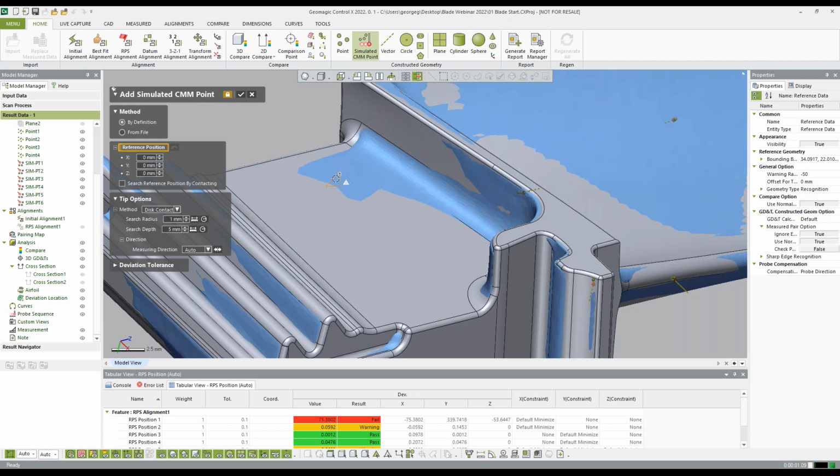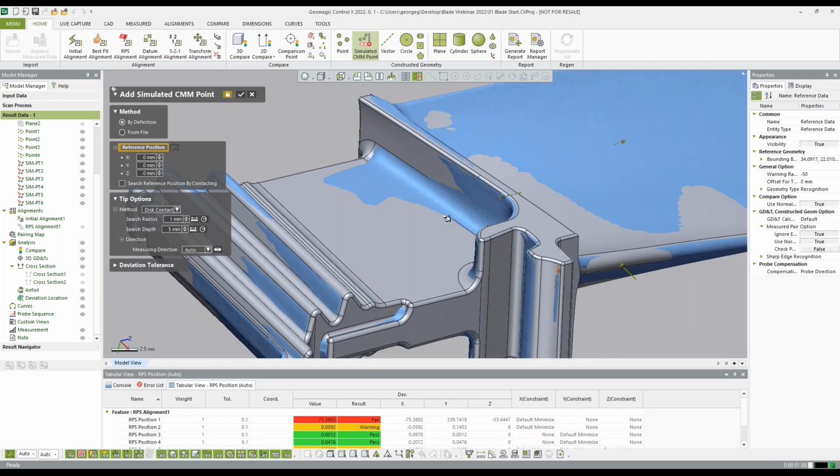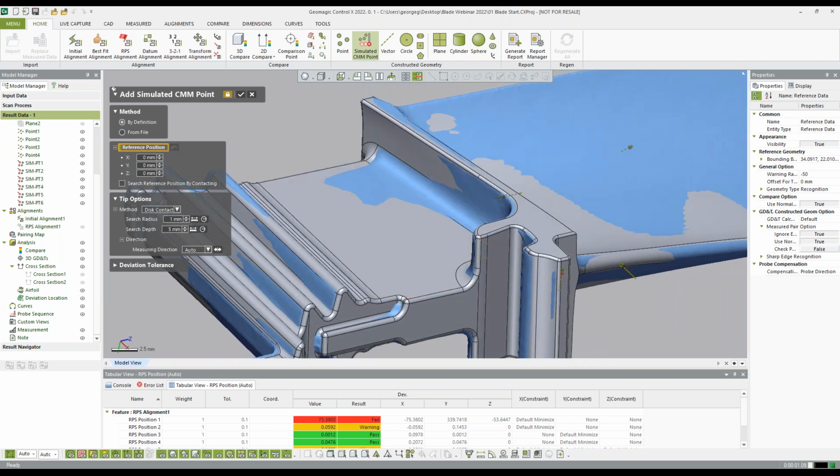Sometimes, for example, if I need to measure this plane here, that measurement between that plane and this plane might be slightly different because, you know, if you measured that on a CMM many years ago, you're only maybe measuring 5 or 6 points to describe that plane.